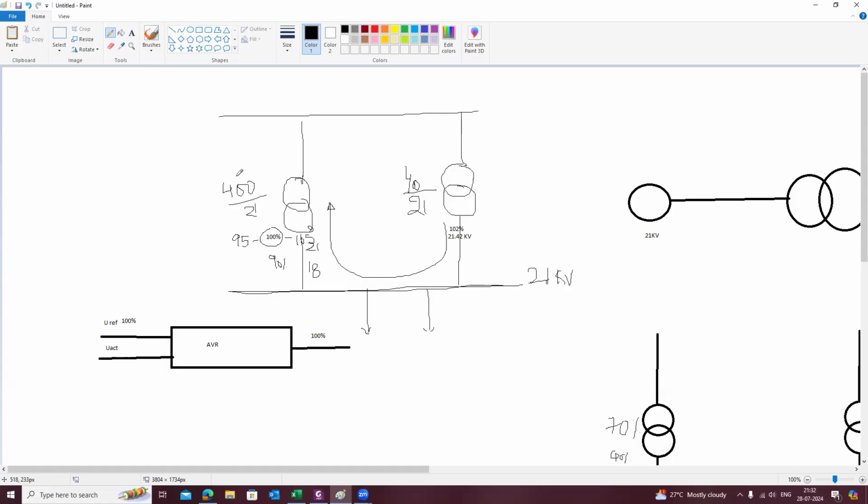See what will happen in the cogeneration industry. There is always a problem of operating at a poor power factor, right? At that time, if you increase the generator set terminal point, what will happen? You are adding some additional reactive power to your loads, right? So the power factor may be improved by improving the generator set terminal point. We will discuss that during our real-time example in our classes, but this is one small example where optimal power flow is needed.